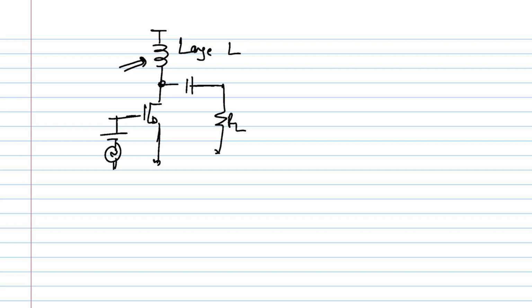Then probably the solution should be that the transistor conducts only for the half cycle in which the load gets the power, and I turn it off in the other half cycle. Then it is likely to give me a better efficiency.